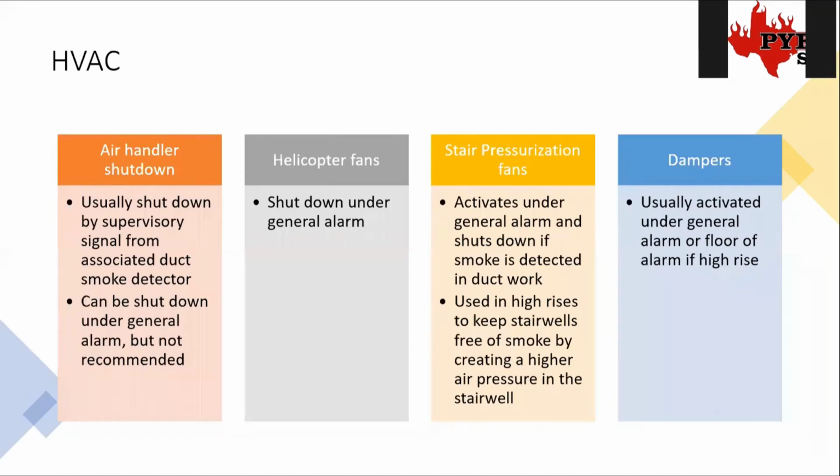Then we have HVAC. If you don't know, HVAC is short for heating, ventilation, and air conditioning. So the first thing that I put in there is the air handler shutdown, because when you think about heating and air conditioning, those are your air handlers. These are usually shut down by the duct detector that we mount on the ductwork.